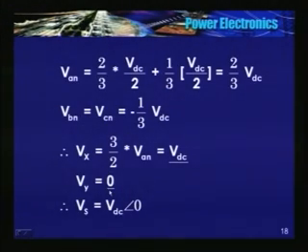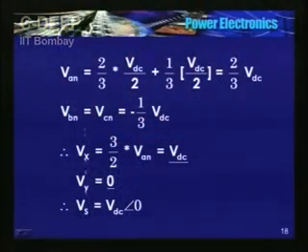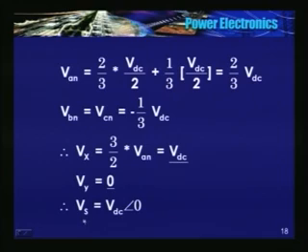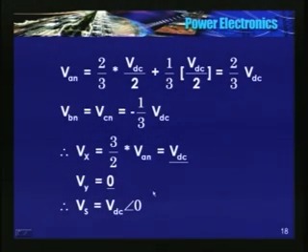So what is the space vector? Magnitude of the space vector is Vdc itself, because y is 0, square root of Vx squared plus Vy squared, and angle is 0, tan inverse y by x, y is 0.